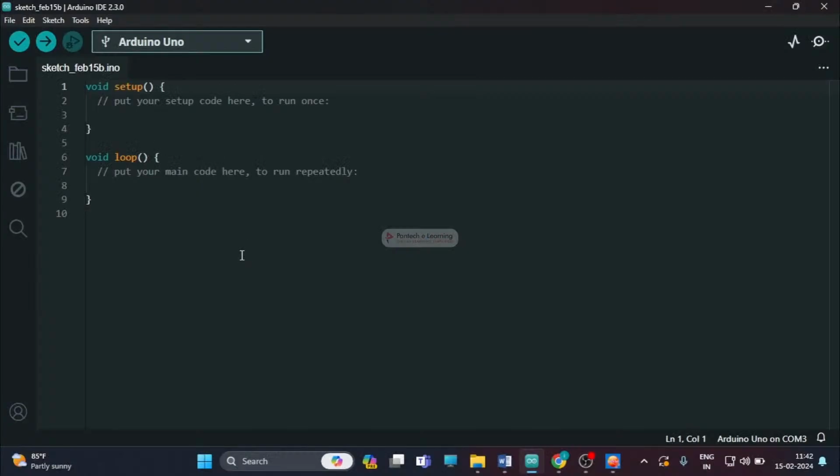So now we are going to write another program using the AccelStepper library. Here we will use an advanced stepper motor library, which is the AccelStepper library. It outperforms the standard Arduino stepper library in the following ways. Like it supports acceleration and deceleration. It supports half step driving. It supports multiple steppers at once with independent concurrent stepping on each stepper.